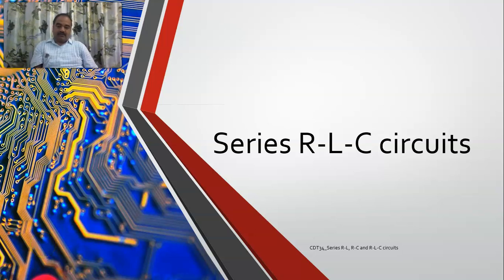Now we will move on to the series RLC circuits, which are a combination of both RL and RC circuits. You can have the characteristics of both RL and RC circuits by adjusting the inductance and capacitance. You can have either an inductive based circuit or a capacitive based circuit. You can get the characteristics, either inductive or capacitive, simultaneously, or if you balance them both, you can get a resistive characteristic also.